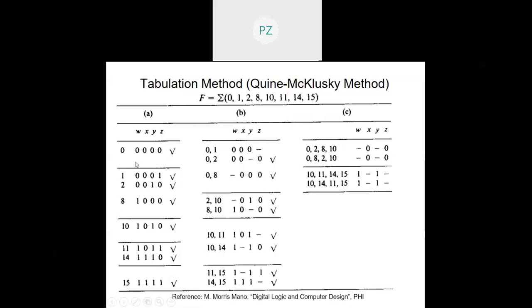So when I combine these two, I can write 0 8 can be combined because they are varying in just a single bit. So it will be dash because this is varying, and then 0 0 0. So I'll write dash 0 0 0. So that pretty much takes care of these two groups and their combination.